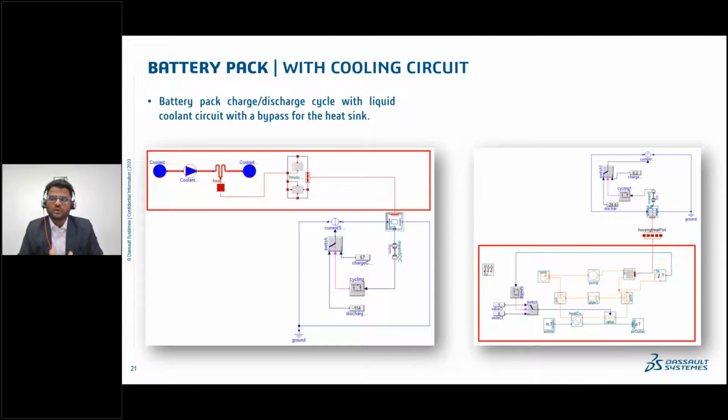As a next step, once you have determined your thermal values and your entire battery pack structure, the tool also helps you with the capability of defining a cooling circuit around your battery pack. This cooling circuit could be a simple cooling circuit with just an adapter and a simple coolant flowing through your battery pack, or it can be a detailed cooling circuit with different heat exchanger control switches, control valves, and different coolant studies at a particular temperature. You can define your coolants, and those sorts of things can be done using various libraries which are already present within the tool, and these can be used to define the different cooling circuits.